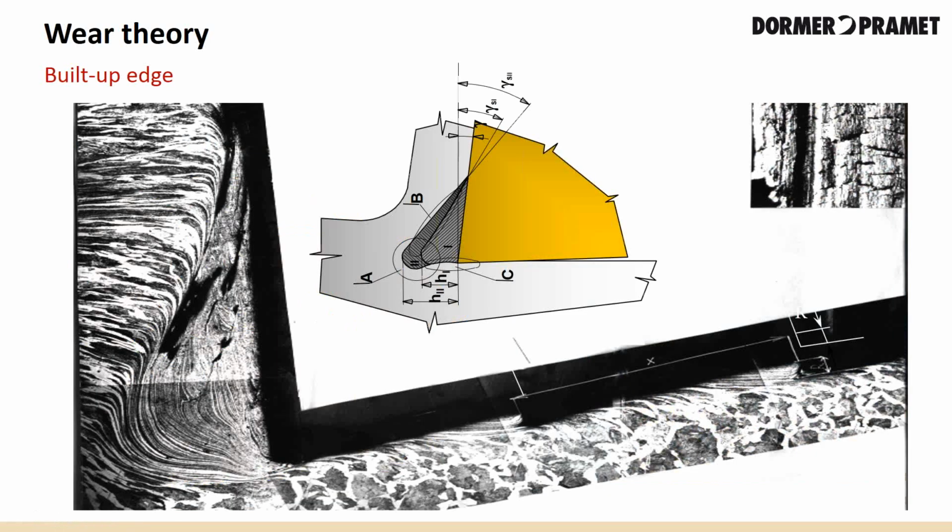Built-up edge is not a stable unit. Usually it has two distinct parts, a stable part which adheres firmly to the top of the insert, and a variable part whose height varies during machining. The frequency of change on the variable portion is quite high and can reach 20 to 50 cycles per second. Particles transported by the chip and by the machined material significantly impair the machined surface, as well as change the workpiece dimension in the radial direction because the built-up material assumes the function of the cutting edge.